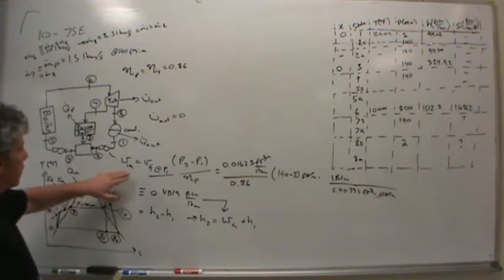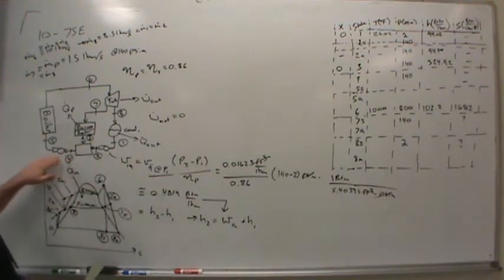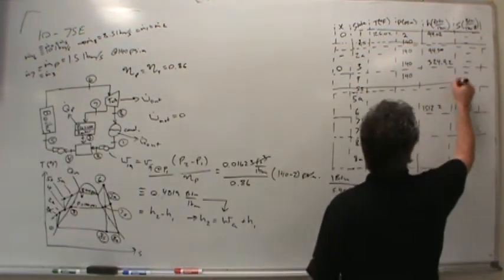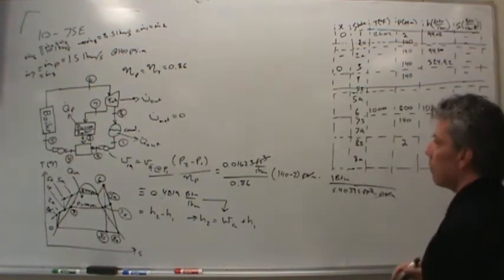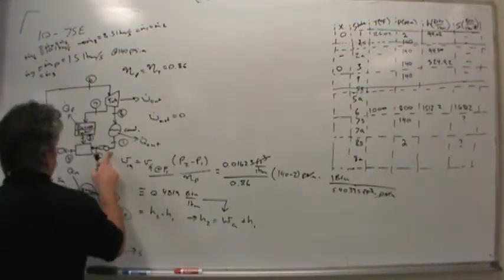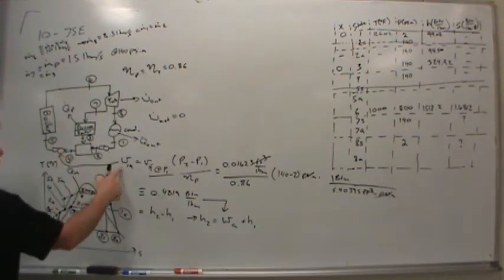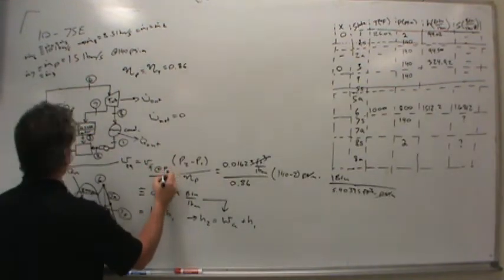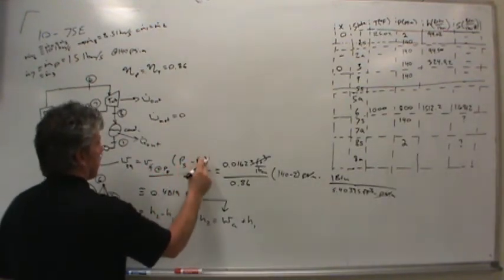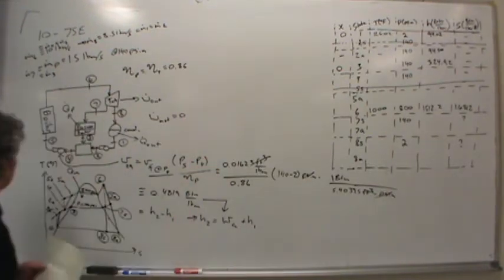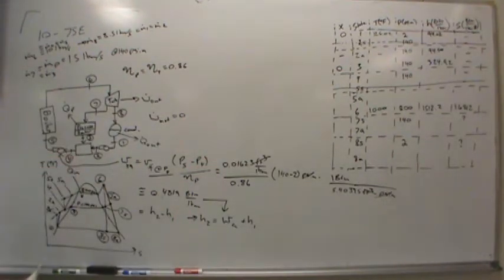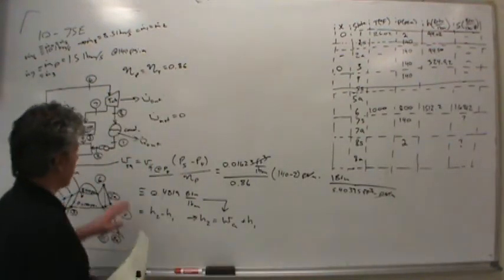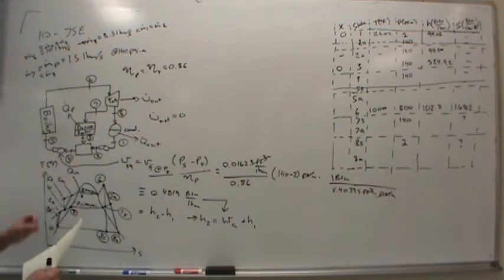Now, because, again, I'm going to use an equation much like this for pump 2 as well, I'm not going to worry about the 5s state. I'll just cross that one off my table, because I could write an equation for pump 2 that looks exactly like this. All I need instead is the pressure at state 5 and the pressure at state 4, and then I just need to divide by the isentropic pump work, and we'll have the pump work for pump 2. So let's do that next.